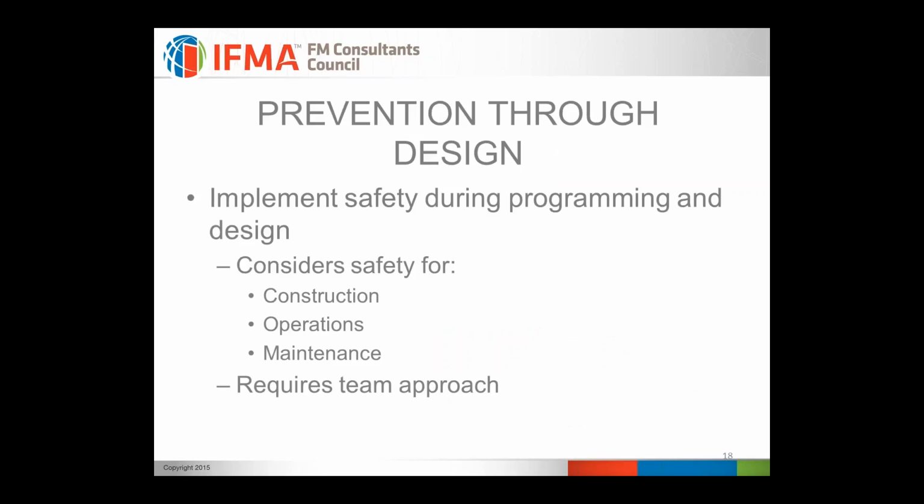If you're really doing prevention through design properly, you're considering construction. So is it possible to modify the design of this new facility so that, for example, the roof system can be built in modules on the ground and then hoisted into place? So it's those types of thought processes that need to be involved, and that's why that bottom point is so important. It requires a team approach.